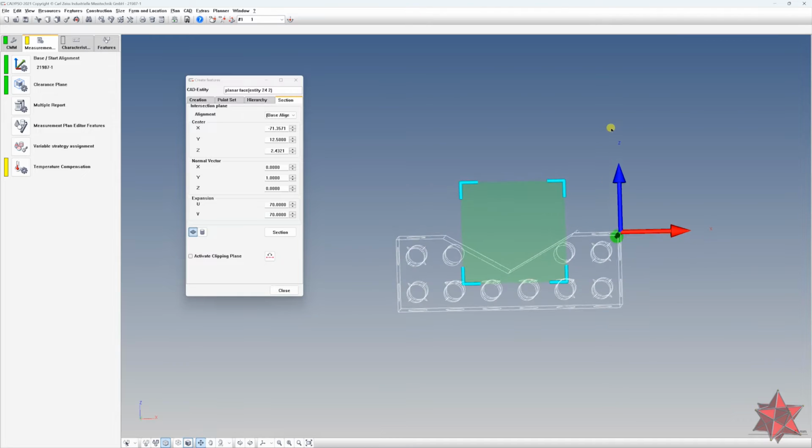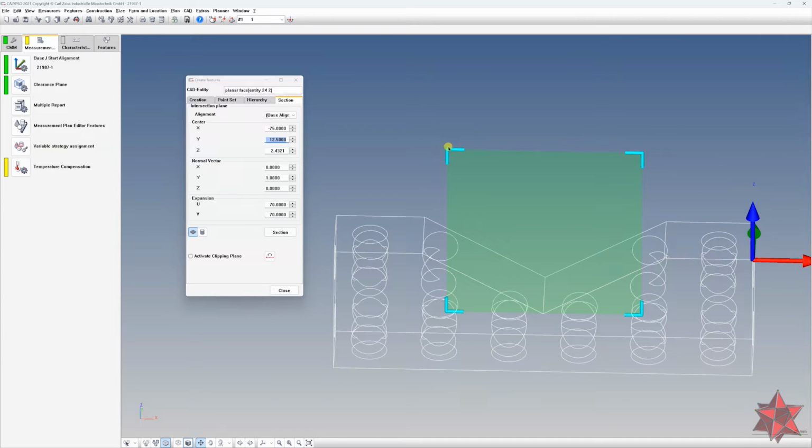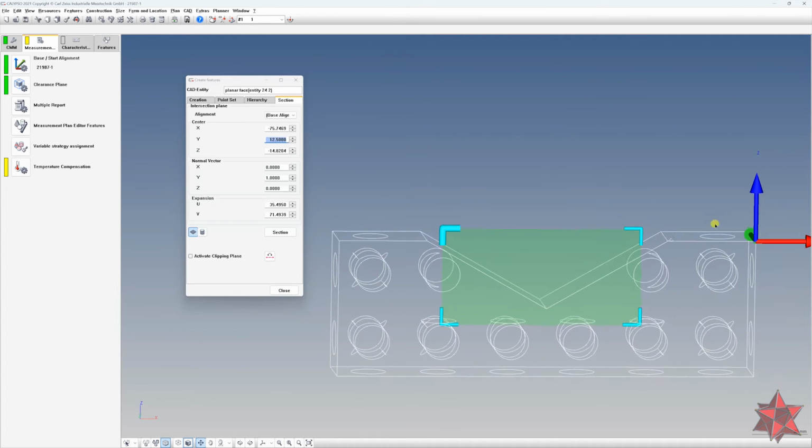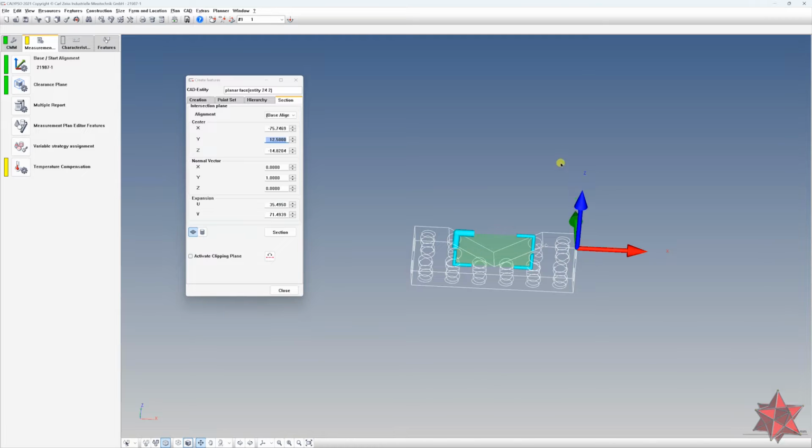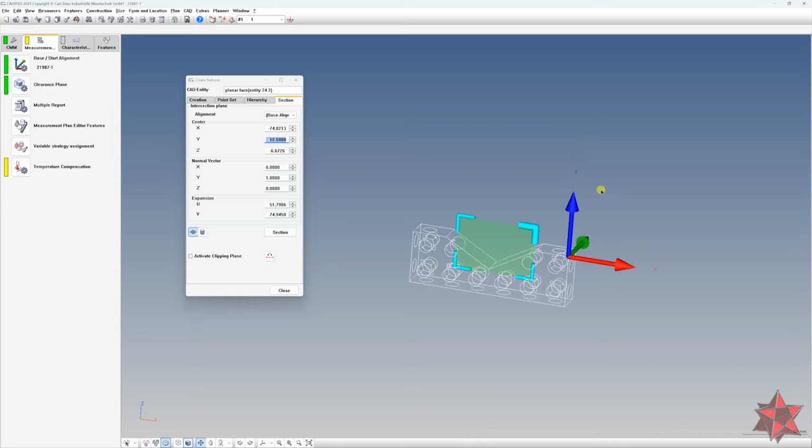90 millimeters left. And we have to divide 90 millimeters in half and add the 30 millimeters. So 90 millimeters, 45 with 30 millimeters, it's 75. And this is how you will manage to make a section according to a length defined in the technical drawing. But we don't have this length for this example.